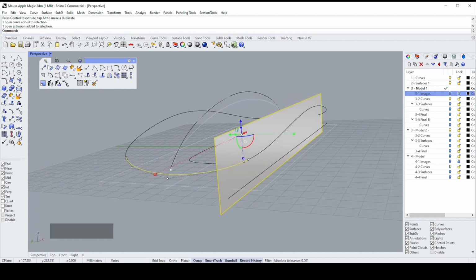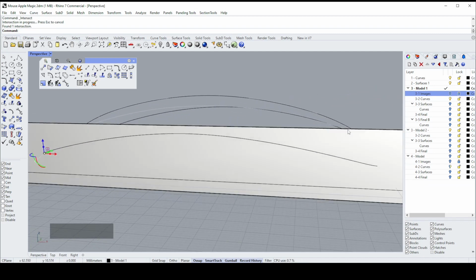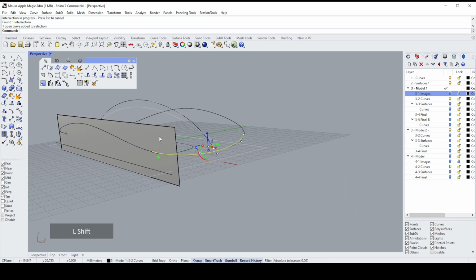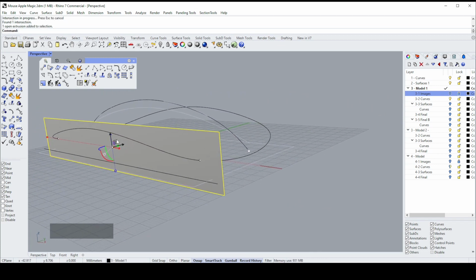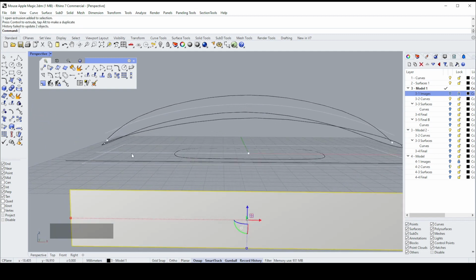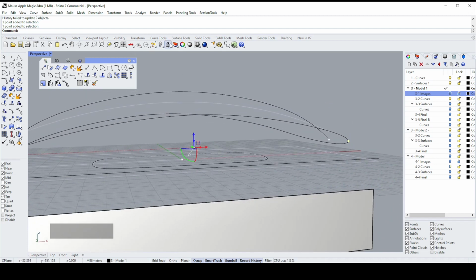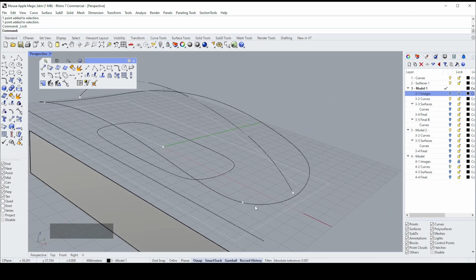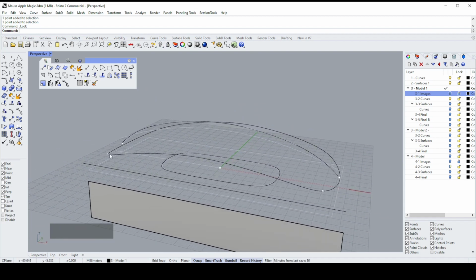And the way to do that is to go to the curve from objects cascade, and this button here, object intersection. If I click on it, I'll get 2 points appearing. Oh, I didn't select this other line. Let's do that again. Right, so there I have 2 points. I'm going to get that out of the way again, and I want to lock these. So I'm going to use the lock command. So now they can't move, and I can get a curve which goes from that point to that point.